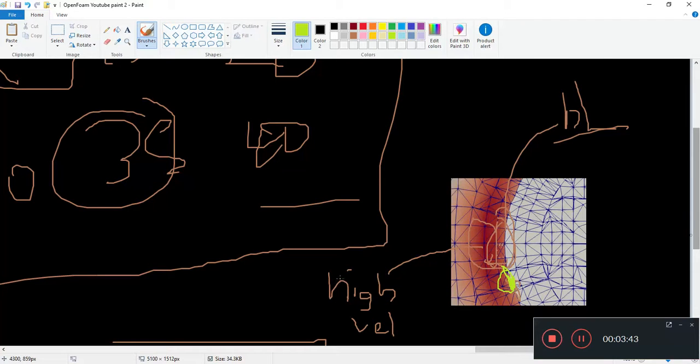So maybe the way to go is to have a smaller mesh so that this boundary layer region immediately adjacent to and outside the sphere is better resolved, so that there's more movement. And the way to do that is, of course, to adjust snappyHexMesh.